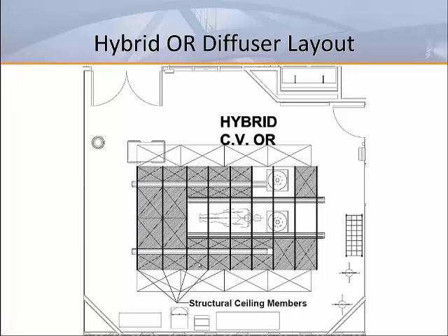This example highlights the complex interdependencies between the selected equipment and requirements for ventilation and air distribution. Early coordination with both trades will enable air distribution to be as effective as possible in preventing surgical site infections. Hybrid operating rooms are rapidly advancing the procedures and treatment for patients. At the same time, they are developing new and innovative ways to use the imaging equipment, pushing vendors to develop newer devices with more functionality and higher resolution.